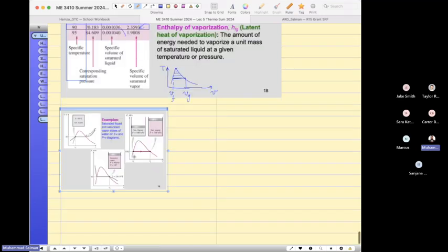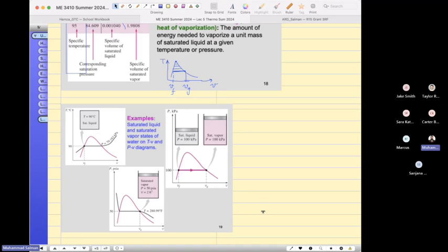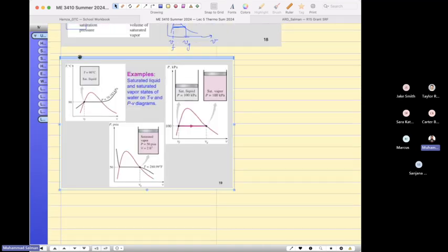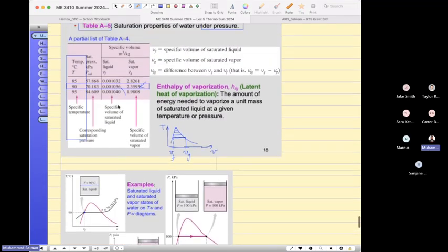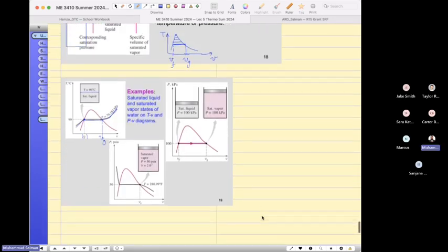Okay, now we go to the next slide. The example is just telling us about this liquid line. This point is given at 90 Celsius, saturated liquid, and the pressure over here is 70.8183. You will draw a constant pressure line. As I mentioned, constant pressure lines are drawn like this. This is constant pressure. And how would you represent this digit here? This is VF. This is VG. Again, telling you everything in detail.